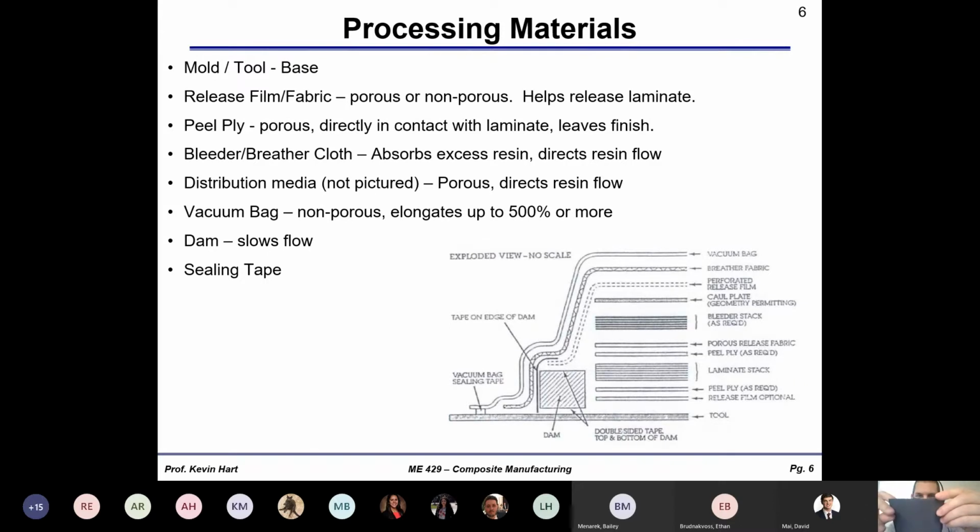And this particular one has, let me make sure I got this right, 6 layers of unidirectional carbon fiber. Remember we talked about the fabric being unidirectional, all in one layer. So I've done that here. I've stacked the carbon fiber 6 layers on top of each other, and then I put this on an aluminum plate, put it in an oven, put some pressure on it, and let it cook for about 2 hours.